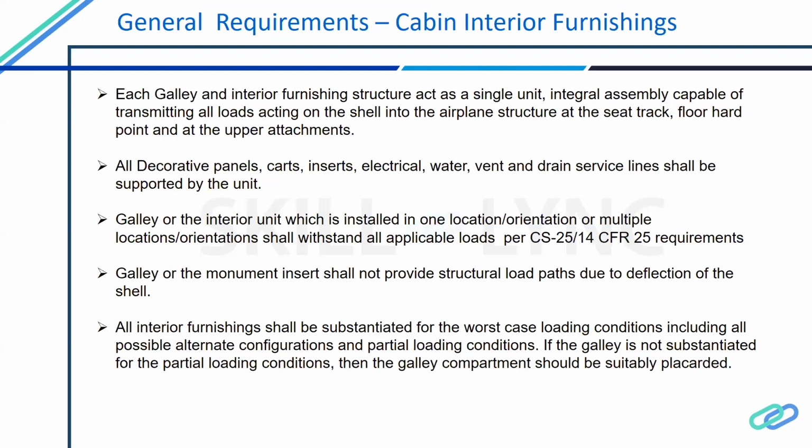And these galleys or the monuments should not come free when there is a crash case, or when the airplane is in diving mode, or when the airplane is landing. They should not come loose, and they should not cause any injury to the occupant. So all these monuments should be able to act as a single unit and take the payloads. Whatever load is there, they should be able to withstand that.